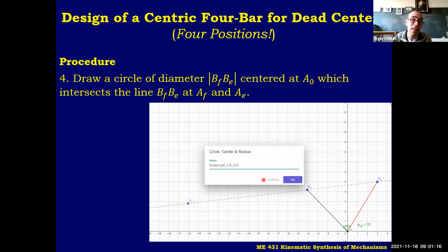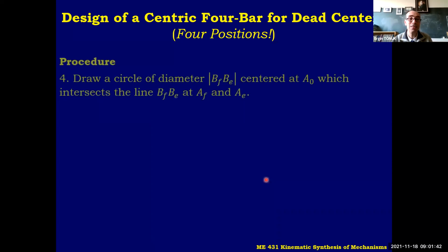You just write it, and you may even make this angle variable to change your design if you like, okay? That's the good part of parametric packages, and you can do it with CAD software as well. Okay, so this is just the trick that I do, okay? Measure this distance, and since it's the diameter divided by 2, that's the result.